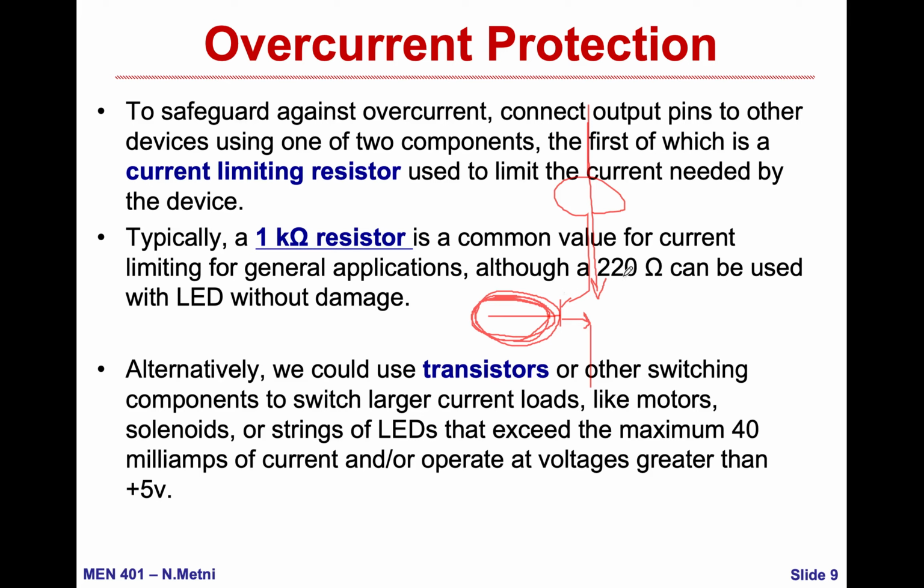So this transistor is only a switch, and the switch is controlled via a microcontroller, sure, with a current limiting resistor. Here, no matter what current is flowing, it's taken from the VCC, so it's not affecting the microcontroller.